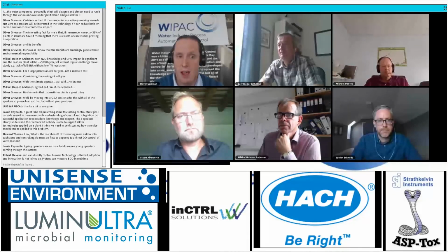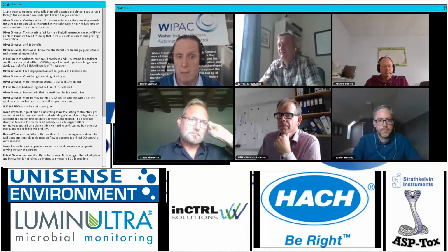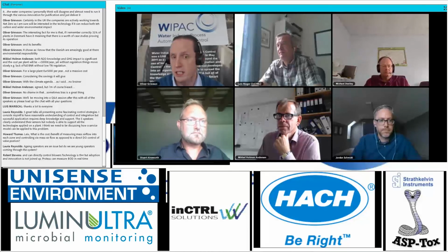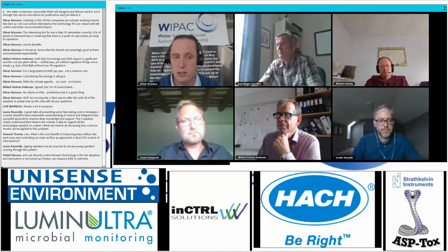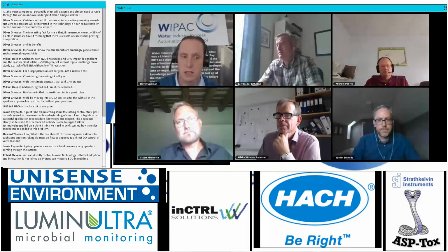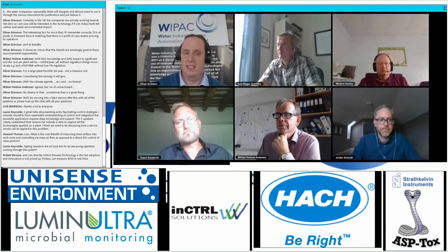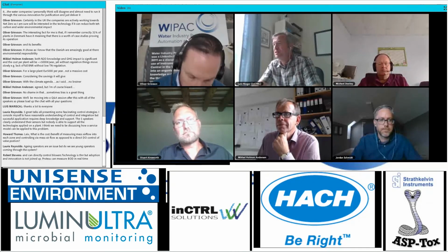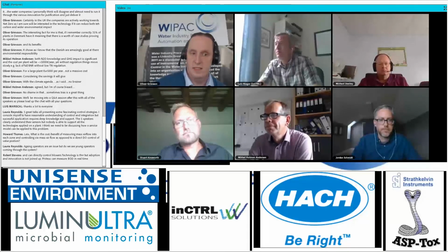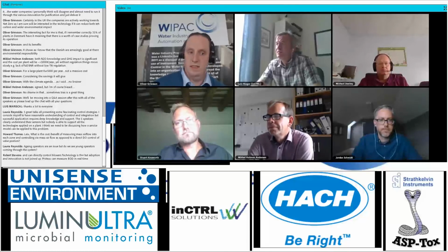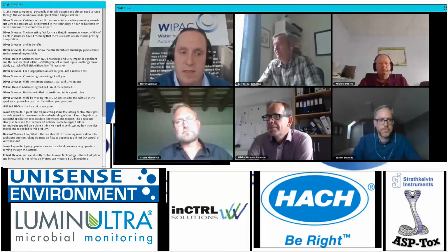Question from Howard Thomas of Thames Water. Leiv, what is the cost benefit of measuring mass airflow into each zone and controlling via mass airflow as opposed to a direct DO control of valve position? Yeah, so there are a couple of reasons for doing that. One is that you linearize the valve, basically having an additional control loop in there. The other one is that if you are not measuring airflow, you cannot put bounds in, right?